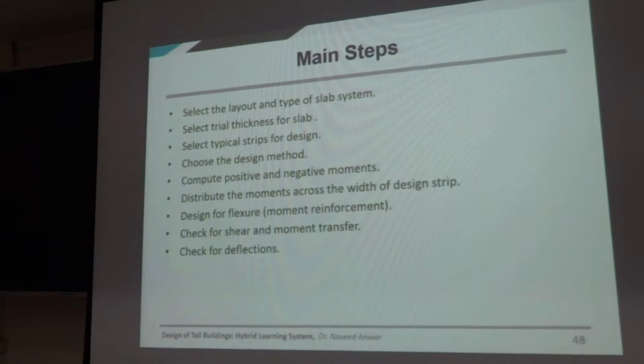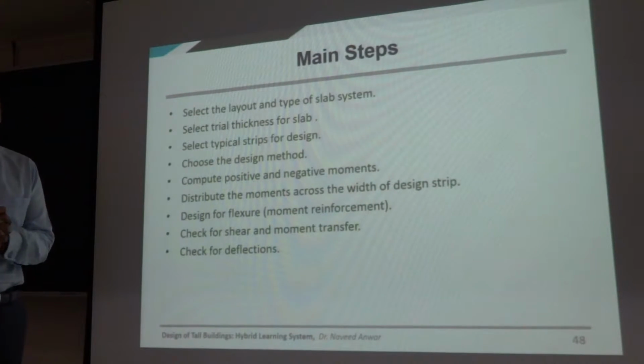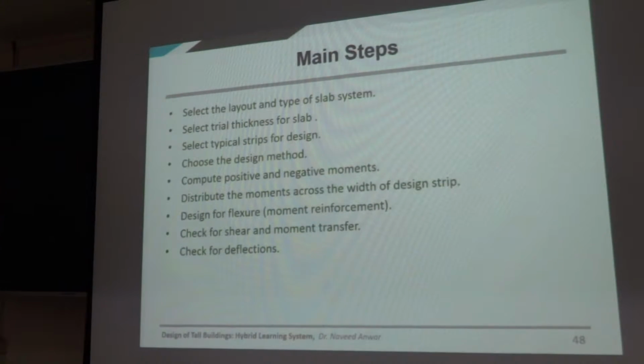This is the main step, how you do the design. Select the layout and type of slab system. Select trial thickness for the slab. Select typical strip for design, because there will be hundreds of strips in a real building. You cannot design every strip.